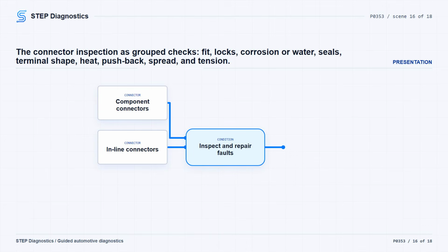If the coil swap did not make the fault follow the coil, check the related PCM and component connections. Handle any applicable bulletins first. Disconnect all PCM harness connectors, any related inline harness connectors if equipped, and the related component connectors. Inspect connector installation, connector locks, corrosion, water intrusion, weather seals, bent terminals, overheating from a poor connection, terminals pushed back into the cavity, spread terminals and terminal tension.